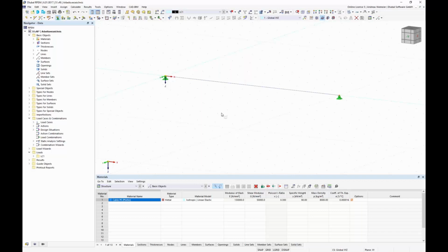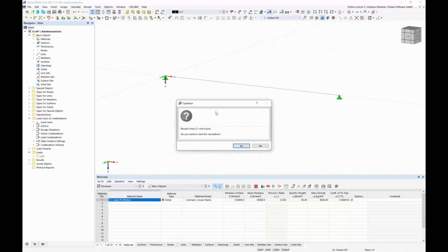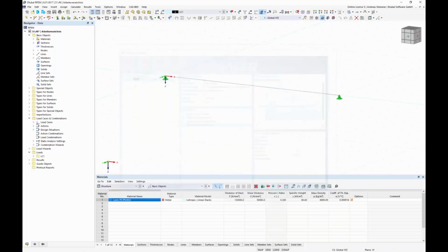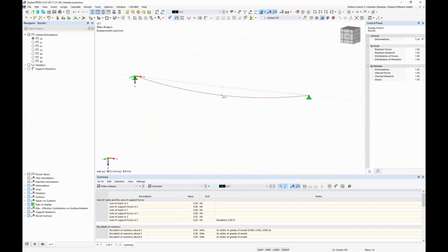And of course what I always do when I explain form finding, I calculate the deflection of this easy example. Therefore let's calculate the self-weight load case, which is always defined automatically in our program. If we run the analysis of this load case, we will get from the program, as expected, a deflection curve. Here you see 66 millimeters sag.